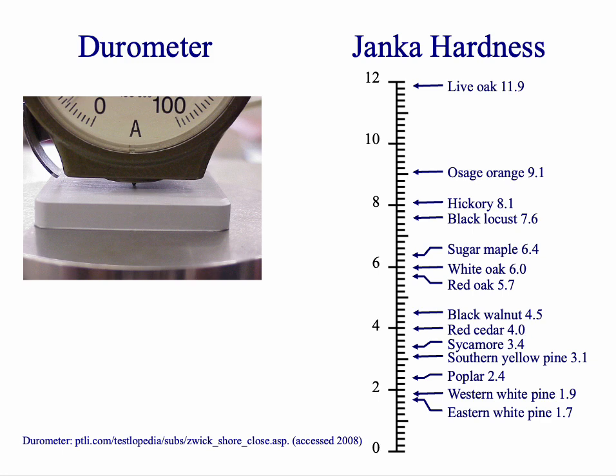We have other methods of measuring hardness of non-metallic materials. Rubber hardness is measured with a durometer, similar idea to Rockwell. You measure how deep the penetrator goes into the test specimen. Wood hardness is measured on the Janka scale. A 0.444 inch diameter steel ball is pressed into the wood to 1/2 its diameter. The force required is the Janka hardness.